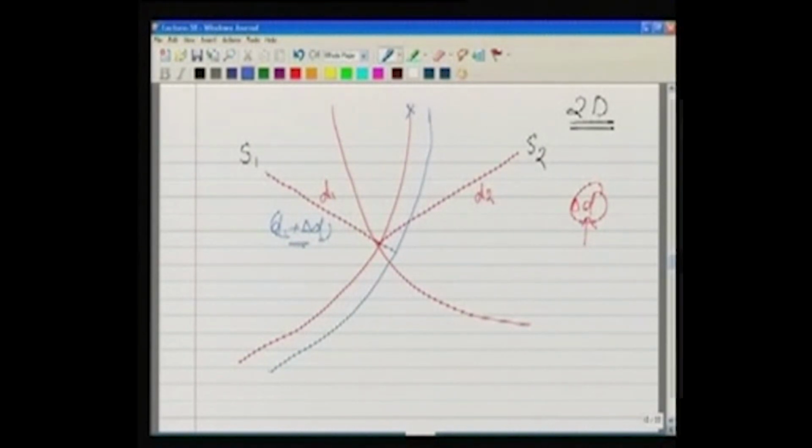Now from the second satellite also, we will be measuring d2 plus delta d. That means we should be somewhere along this circle from S2. Now what does it do? It will shift my position from the actual position by this amount. So the point P has been shifted to P dash. This is the effect of the error. My delta d has shifted my point from P to P dash.